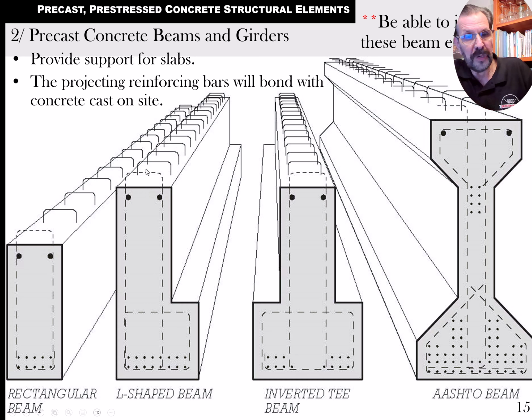Then this rebar that you see sticking out of here, and then you pour concrete across the whole surface of the bridge deck, or a floor deck or whatever. That gives you concrete that's connecting the double T, which might have a real rough finish on the top so that it can bond better to all the concrete and all this rebar sticking up. This becomes a joining system. So I'll show you some pictures of that in a little bit here.